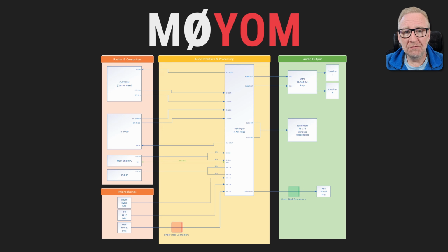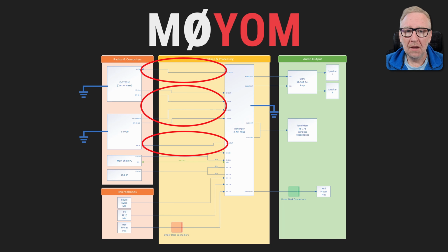By this point, you should have a pretty good idea about ground loops and how they can be dealt with. Let's take a look back at the original audio design schematic for my station. If we add in the grounds for the equipment I'm experiencing issues with, we can see that there are a number of ground loops that exist, primarily these. We can now incorporate the DI boxes and the line isolators into the design in order to eliminate those ground loops.